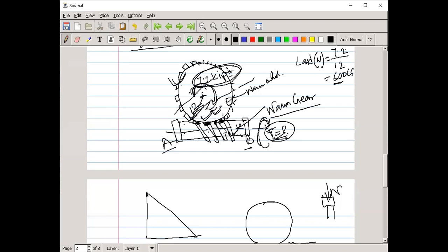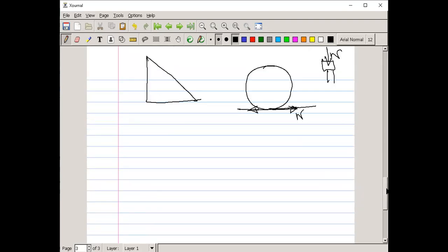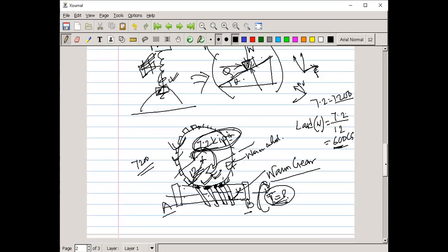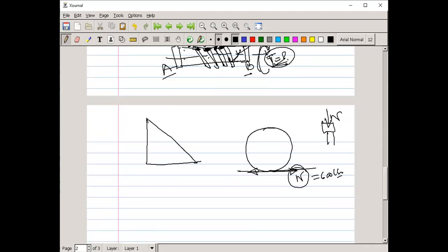And when the meshing is there, there is loading. Suppose one gear needs this amount, 7200, which is very high, so this amount of moment is needed for this wheel. So at the junction point there is a huge load. Understand? Huge load. That load we define as W, which is nothing but 6000 pound. Here 6000 pound. Up to this, is it clear?